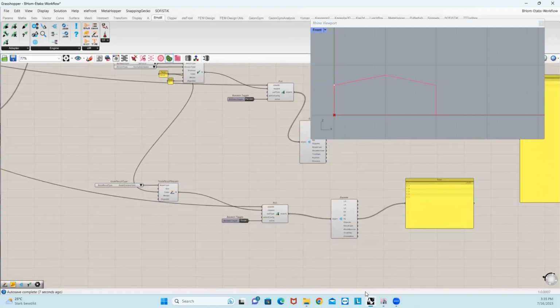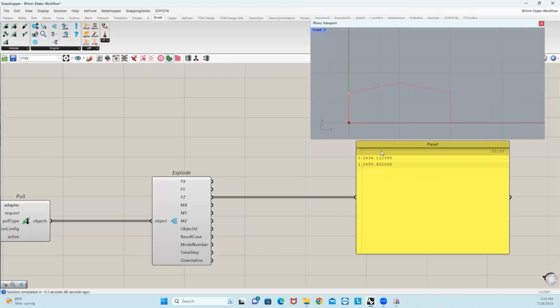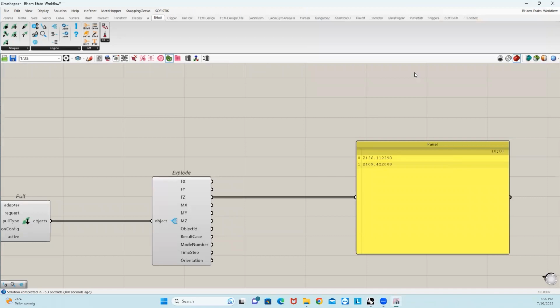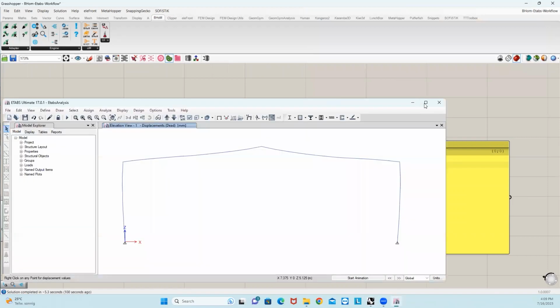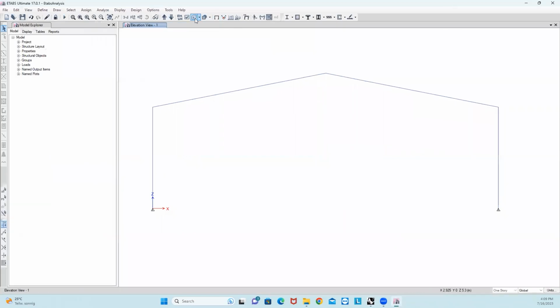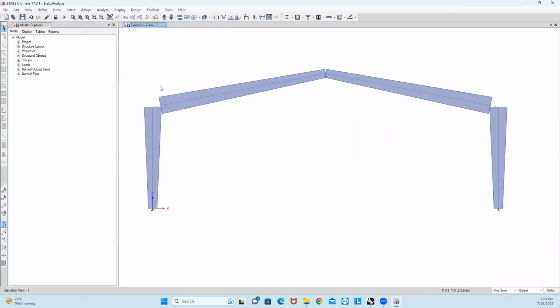So that's how we can extract our nodal results. Guys must have noticed this point, like the nodal directions are not the same, like at this point and as this point, although our columns, they have the same length and the rafters have the same length. The reason behind this is the end length offset. So if you just check the extrude view, you can see that we have this end length offsets here. And that's the reason it's not equal.